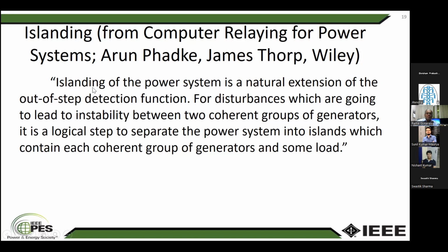Islanding of the power system is a natural extension of the out-of-step detection function. The out-of-step detection that I was telling, detection or prediction. For disturbances which are going to lead to instability between two coherent groups of generators, it is a logical step to separate the power system into islands, which contain each coherent group of generators and some load.